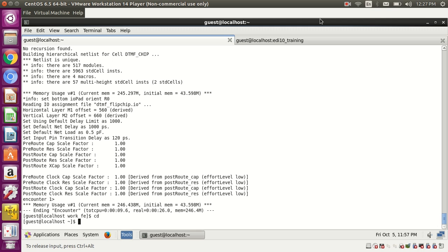If the customer is okay with cost and all those things, then finally they will give a 50% netlist, which is called NLA. Even some 30% netlist, then 50% netlist is called NLB, some 70% is called NLC, and the 100% netlist, most of the blocks will be 100% in NLC itself, but some 30% of the blocks will be in our partitions, so they will not be there. So NLD, the final release, is NLD. Even if any changes are there, they will call it a functional ECO.